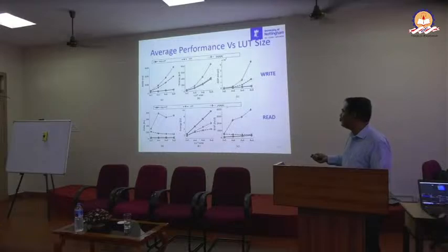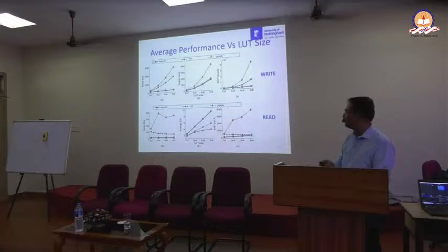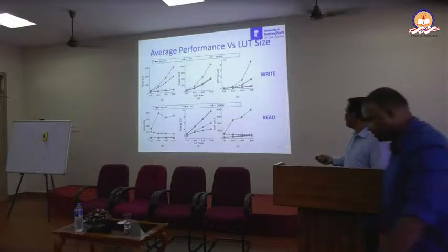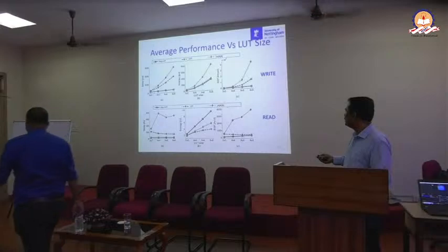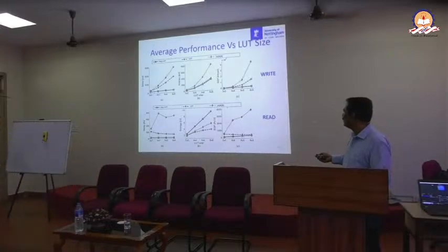Size, the delay almost remains constant because we are writing simultaneously to all the memory strings. Similarly, if you look at the write energy, it almost matches the previous method, but that's all right because we are compensating with the delay. And when you look at the PDP, the EDP, the energy product with the delay, the presented method is doing much